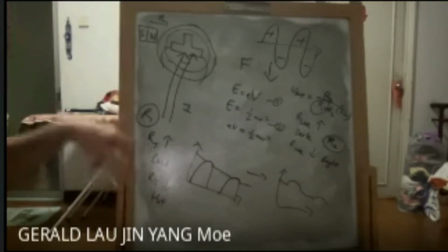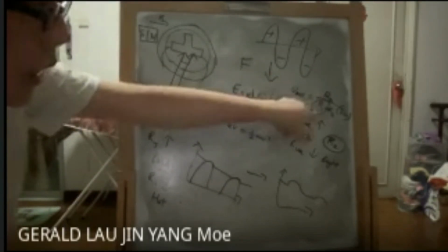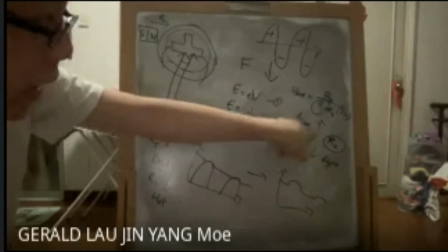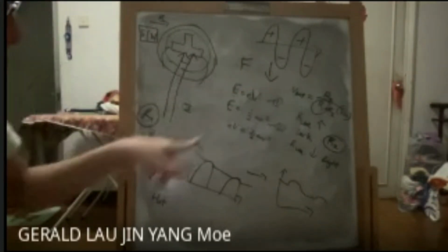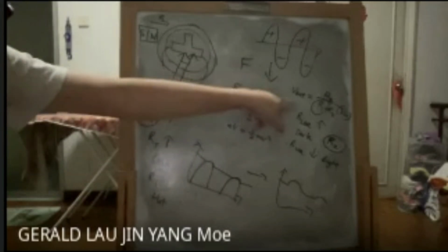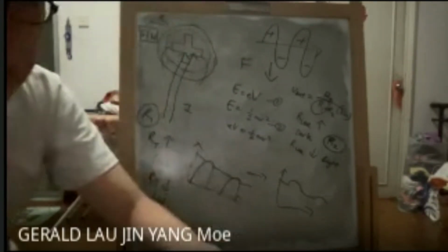Based on the resistance, then you understand. R2, directly or inversely? R1, directly or inversely? If LDR resistance goes up, voltage will go up. But the thermistor is inversely proportional. For the thermistor, if the resistance decreases, the voltage will increase. Yes, very confusing, but try your best to understand.